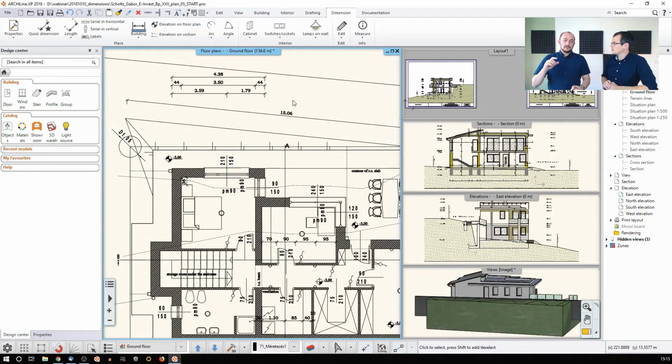Now, there is one thing you should consider if you are in a situation like that: you can break this associativity connection link to these items if you want. There could be a scenario when you would like to do that. To demonstrate, I will break the connection between this and the window. The other one won't break.